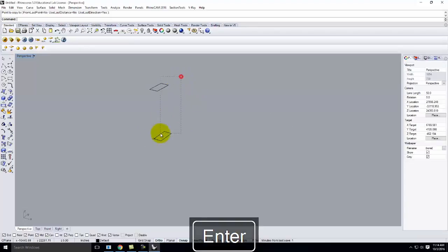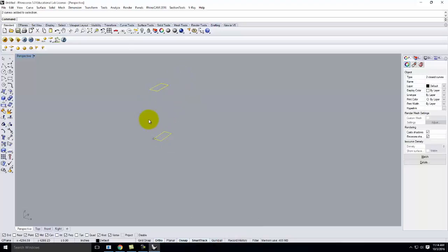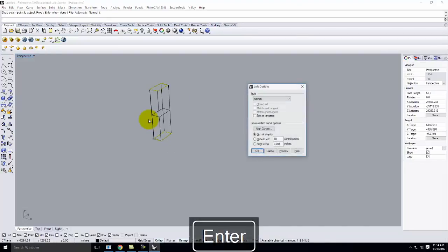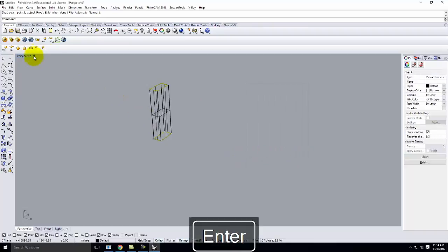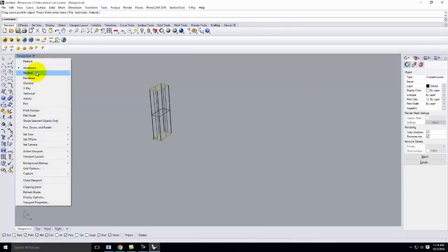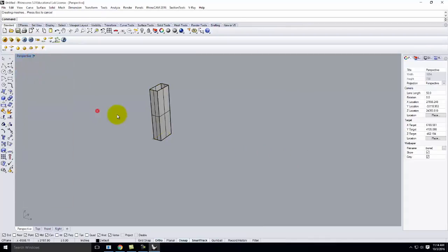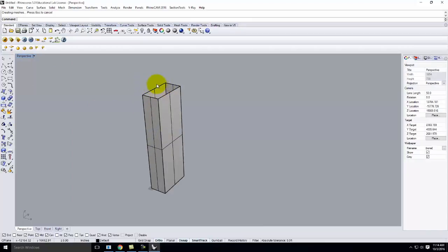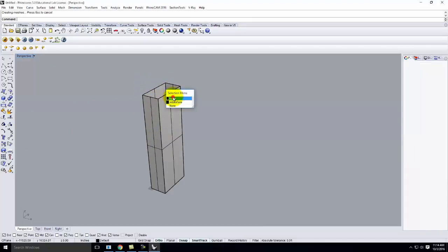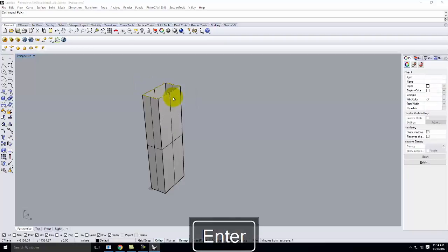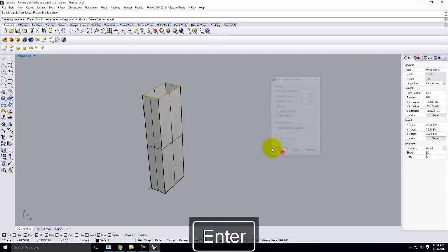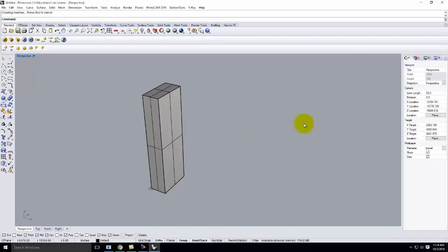Okay. So now in its most basic form, I could take these 2 pieces, I could loft them together, and I could essentially build a very basic rectangular skyscraper. I may want a top and a bottom, in which case I could use patch to create that top for right now. We're going to end up creating floors in the skyscraper anyway, so really all we care about is the external part of it.